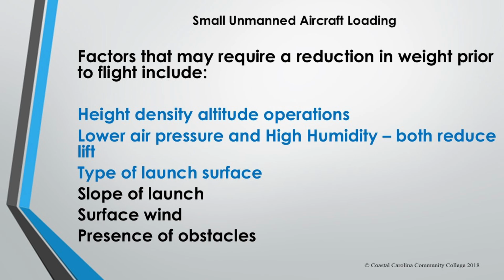Factors that may require a reduction in weight prior to flight include high density altitude operations, lower air pressure and high humidity, which would reduce your lift. What type of launch surface are you taking off from? Is it sloped? Do you have surface wind to deal with when you take off?